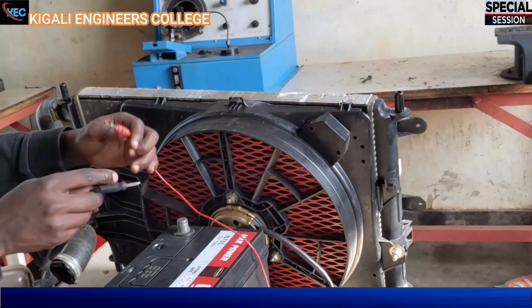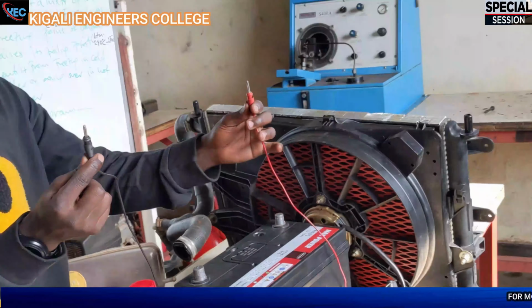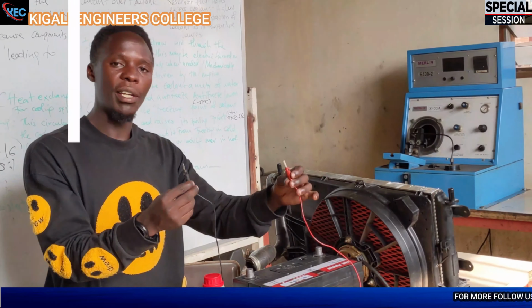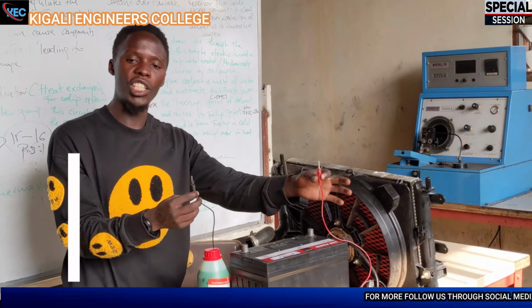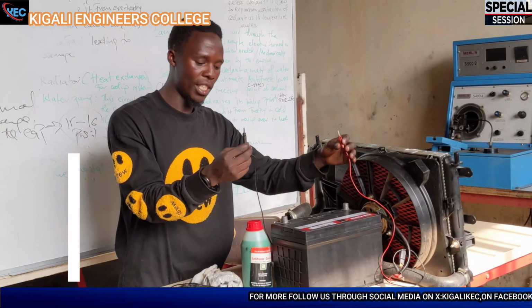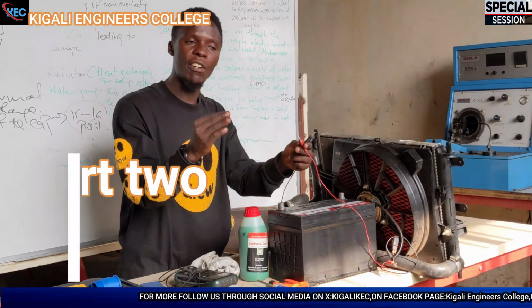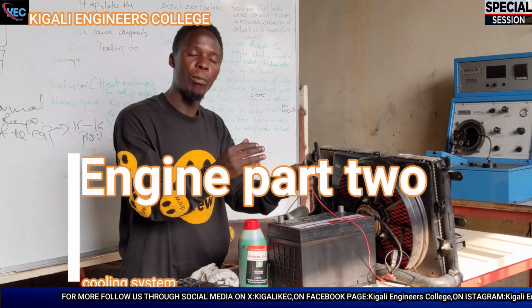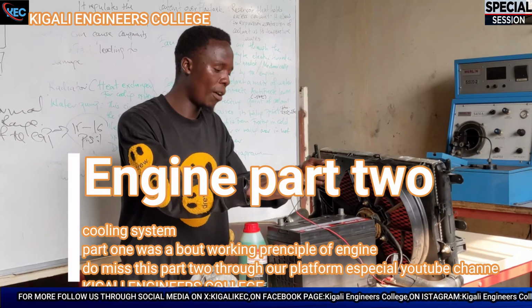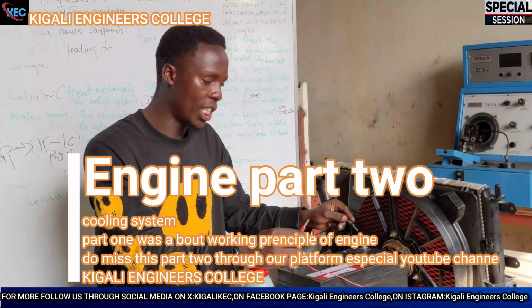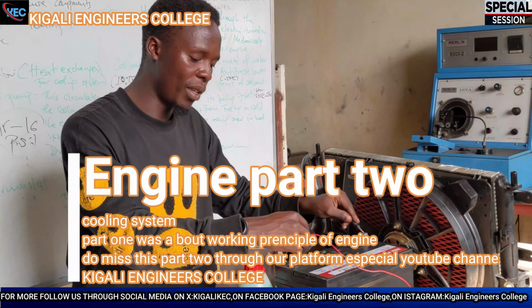But we shall try our best. So I got here red and black. Orange is red and black. Orange is positive and black is negative. But here we have to first of all see how they are connected, so we can get the correct direction of the motor. So we have to put this black onto the negative pin and this red onto the positive pin.